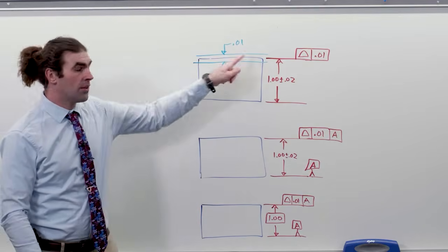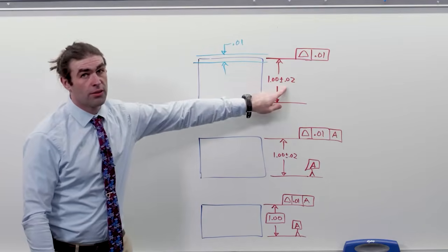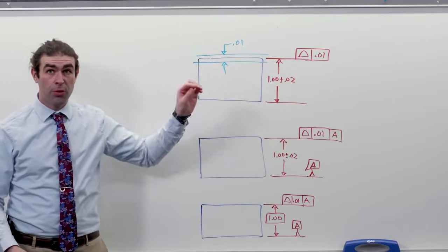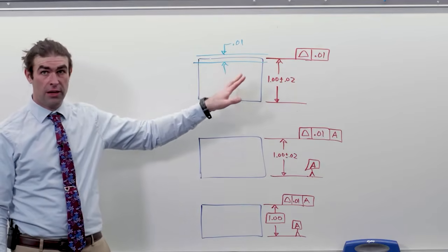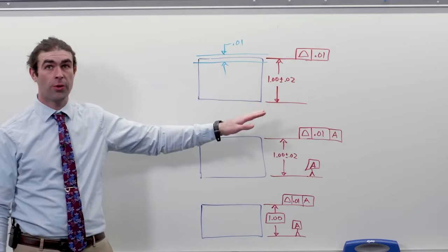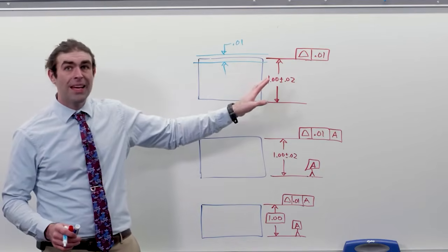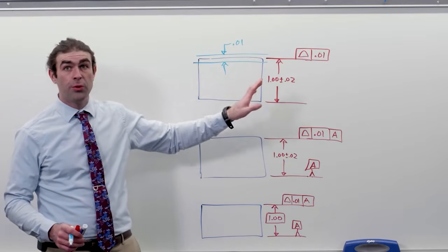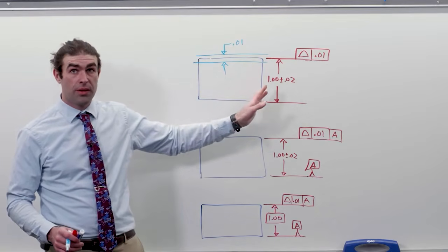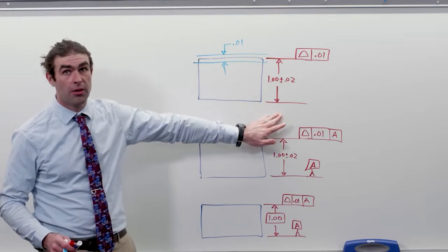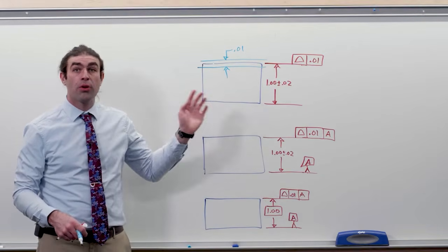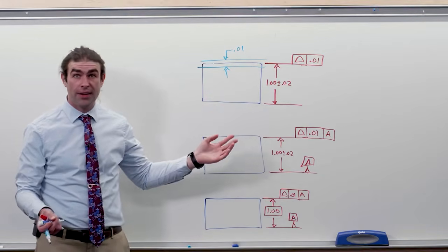Now, this zone must lie within this larger limits of size, so this profile does not control location. The limits of size control location. Now, it would be incorrect to use a basic dimension with this because there's no datum right here. So that's using profile as flatness.